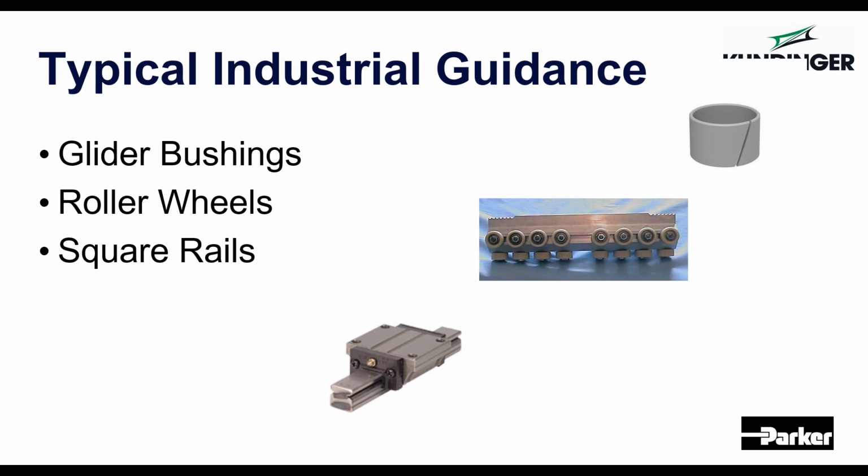So belt drives, a very, very common industrial type drivetrain. So we use synchronous tooth belts, and these aren't the typical black rubber belts with Kevlar reinforcement that you'll see on something like a consumer grade 3D printer. These are polyurethane type belts with braided steel core.